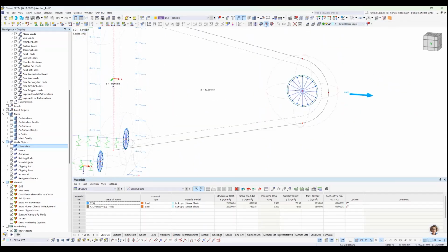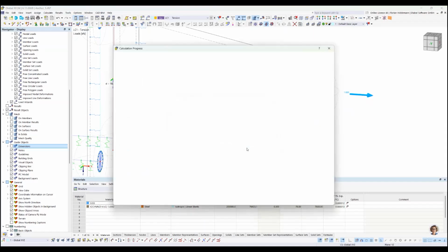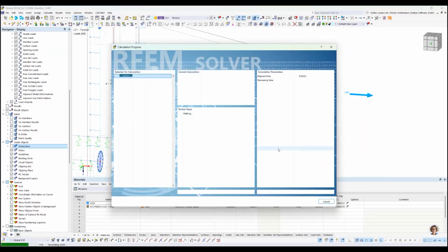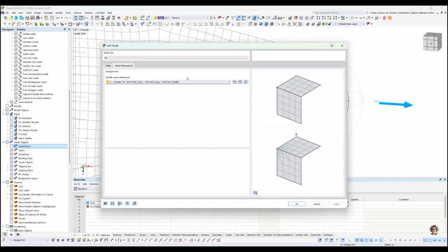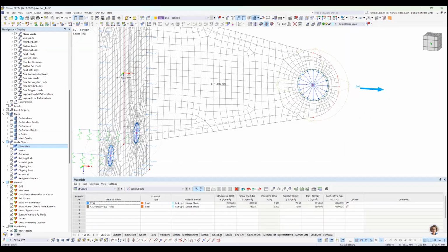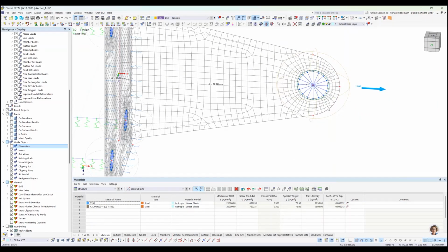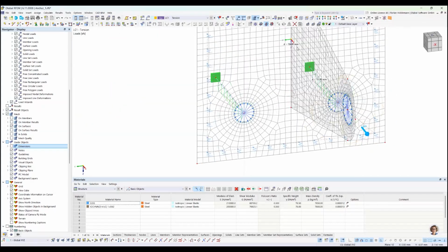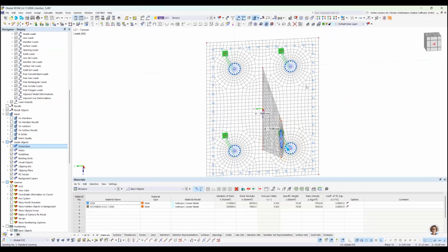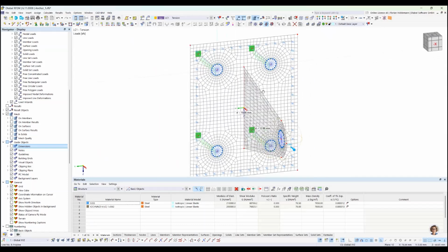Around the structure, there is a mesh refinement. So we would like to see a finer and nicer mesh in this area. Here is a radial node mesh refinement defined, circular. And even if this is bigger than the connecting plate, you can see that we have a nice structure for the mesh. On the plates itself, there are also defined some mesh refinements which make smaller elements, just to ensure that we have a good looking, good distributed fine net here.